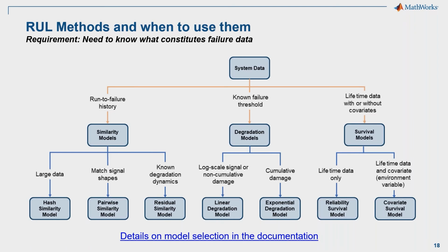This is another view of this, just kind of broken out to more specific ones. And just so you're aware, this is the particular one we'll be using in a second, this residual similarity model, where we have run to failure history with some known degradation dynamics. So we know if it degrades linearly or exponentially or so on.